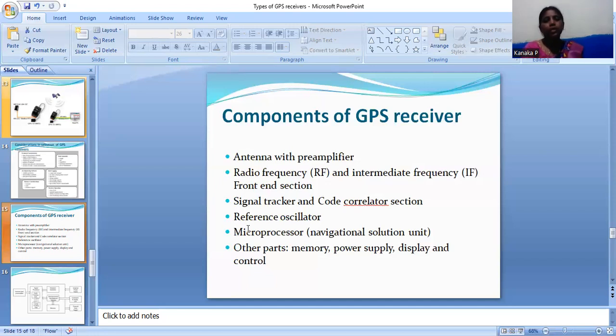Next one is distance measurement. This is the measurement of the slope distance, which the onboard computer uses together with the zenith angle recorded by the line of sight to also give the horizontal distance. Next one is keyboard and display.